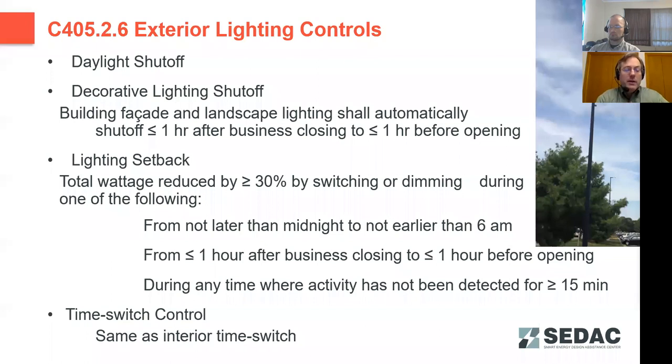Or here it gives you the opportunity to use occupant sensing devices. Now here, and when we were inside, the limit was 20 minutes. Outside, the limit is 15 minutes. And those time switch functions have to provide the same functionality as the interior time switches.